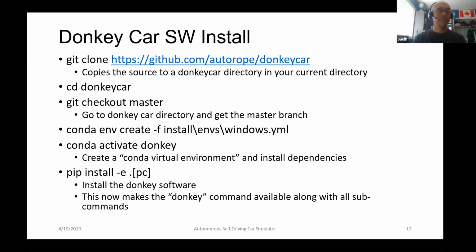I just wanted to put this out there again for people that haven't installed the donkey car before. I just copied what was in the donkey car software docs. Basically, you take the source from the donkey car repo, you change into the directory, you check out the master. This part gets confusing for people as well. This is creating a virtual environment for what you want to use this donkey car for.